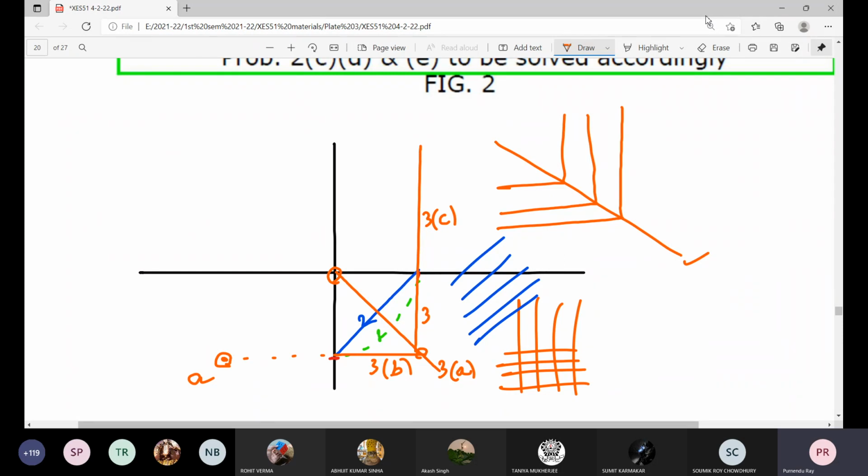For many points, you can draw a single 45-degree line from the point of intersection of the horizontal axis and the vertical axis, then draw a series of horizontal lines, get the points of intersection with that single 45-degree line, and through those points draw vertical lines.